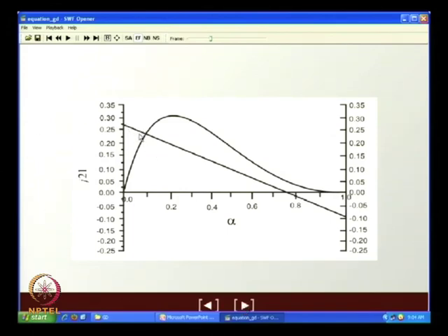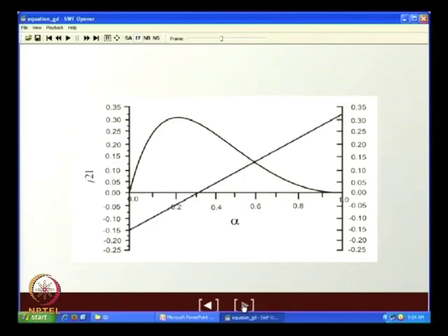We have found out that for co-current upflow, co-current downflow, there is one particular point of intersection. Under all circumstances, this point shifts to higher alpha when we increase J2 and decrease J1, as expected. If we decrease J2 and increase J1, then the opposite thing happens.